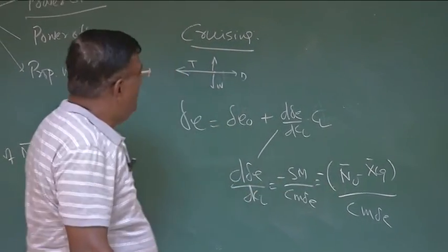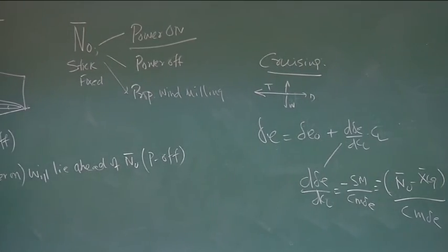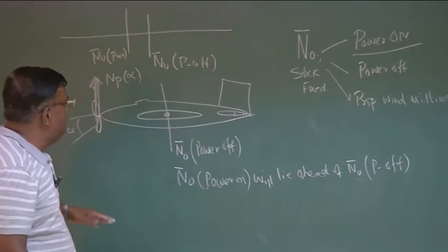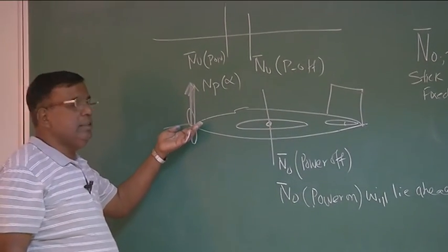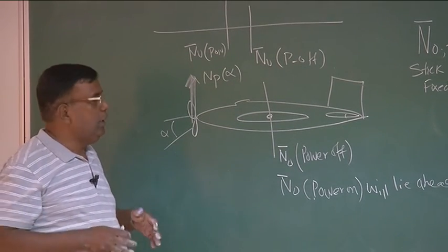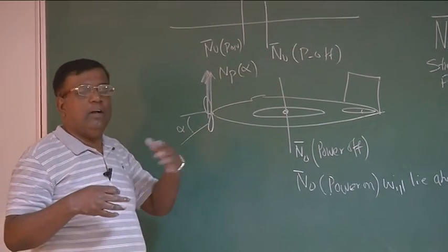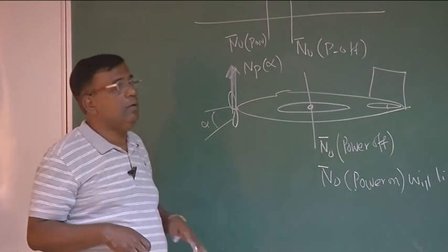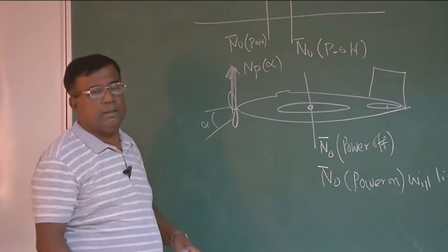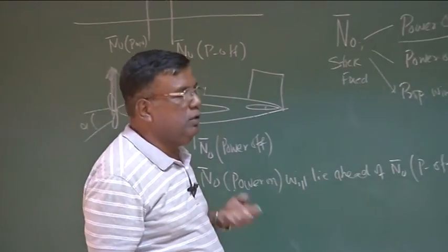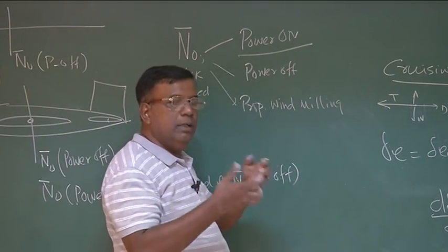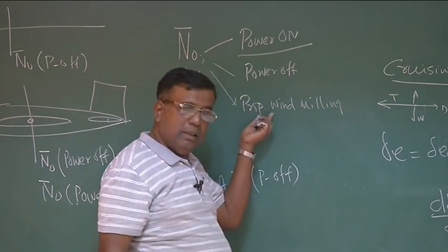Right? But if it is coming for a landing, approaching for landing, generally what happens during landing, theoretically, these engines should be shut or they are clutched, so that although the engine is on, the propeller is not rotating. However, you will see that when it comes down there, because of windmill effect, the propeller will start rotating and generate a little bit of thrust. Although you will find it is recommended you keep 20% thrust, when you say windmilling, theoretically speaking, because of the wind, the propeller is rotating and generating some marginal thrust.